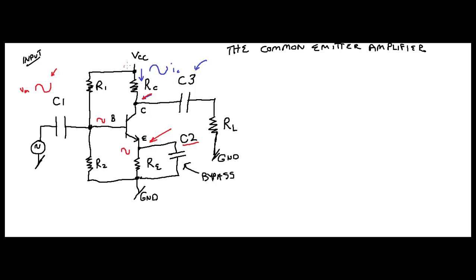Well, let's look at it. Remember, you're starting with VCC, aren't you? So VC, your voltage at your collector, is going to equal VCC, obviously that's what you're starting off with, minus the drop across RC. And that's going to equal IC RC, and I should have made that a minus sign there.